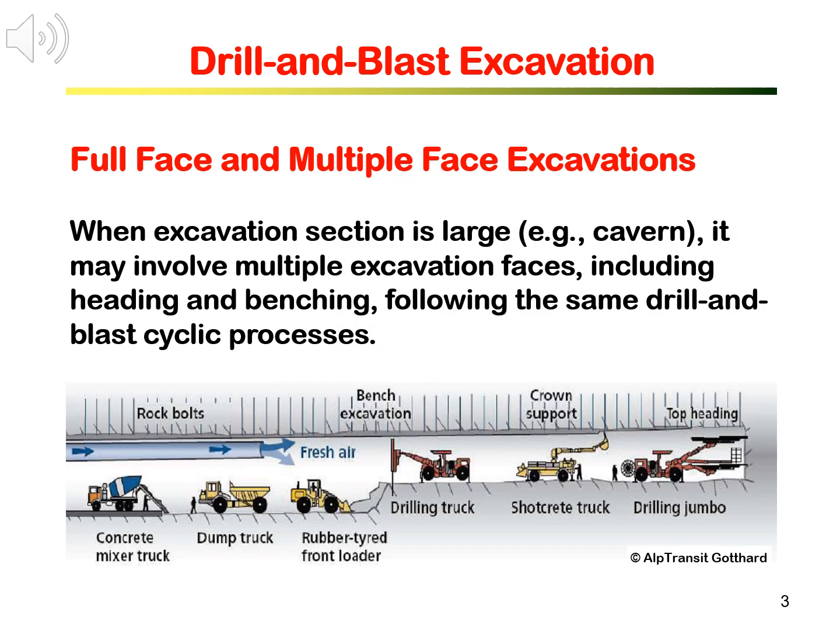Drill and blast can be done with full face or partial face excavation. When the excavation section is large, for example, for a cavern, they may involve partial or multiple excavation phases, including heading and benching. The drill and blast cycle process, however, is the same.